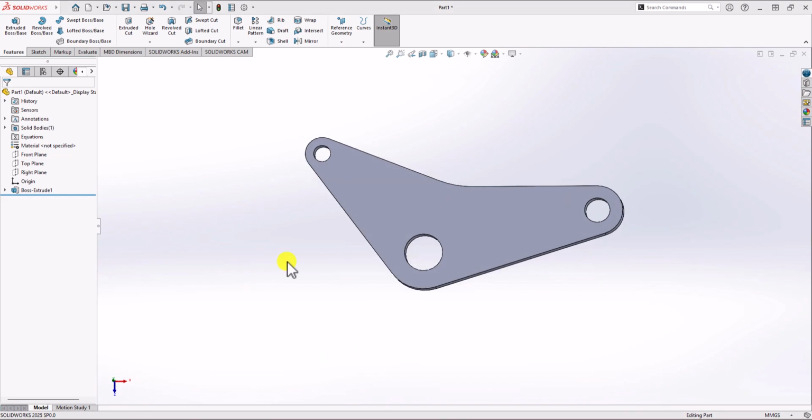Okay, so now it's time to work on the two features that we have on this geometry. I want to first focus on the right feature. In order to make that feature, I need a plane. So the first step is to define that plane. After that, I can make a sketch on that plane. In order to define a plane, as I showed you in a previous video, we need two references. So here, I want to define those references.